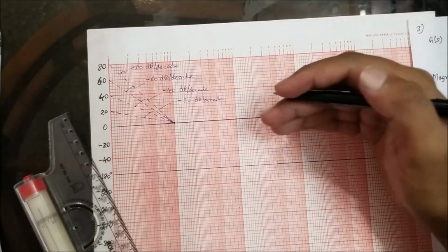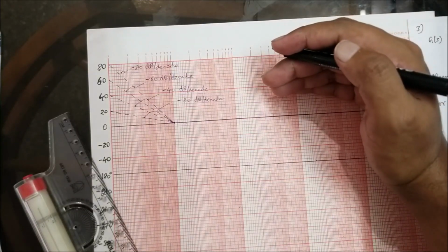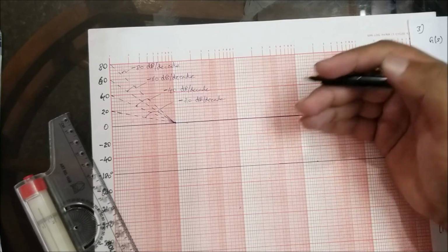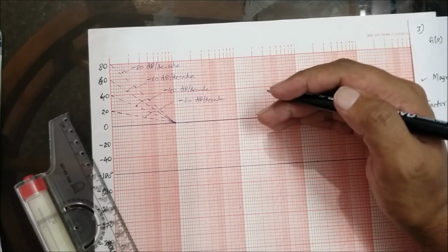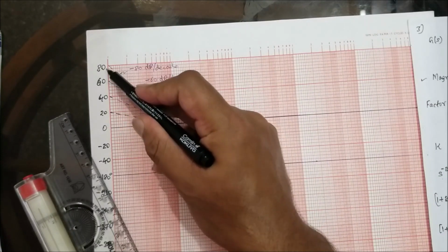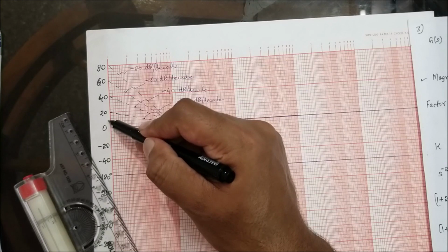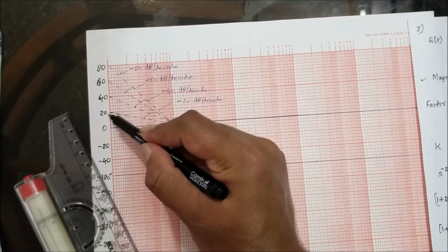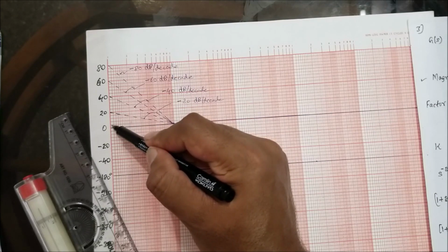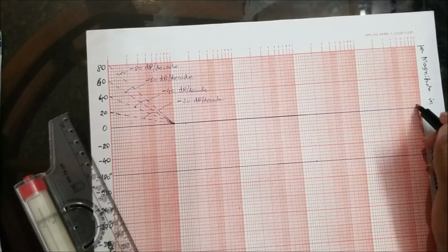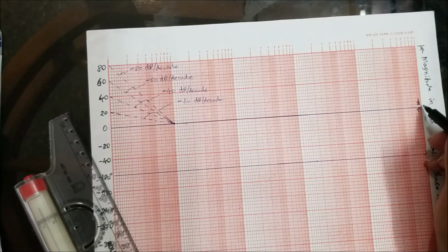The shift measured above 0 decibels is positive shift. The shift measured below 0 decibels is negative shift, right? So plus 12 decibels means I should move upward. You can see here 0, plus 20, plus 40, plus 60, plus 80. I am getting plus 12, so I should move upward. Now for 5 lines I have 20 decibels. Therefore how much is one line? That is 4 decibels. This also you people already know. The value of this is 4 decibels, correct?